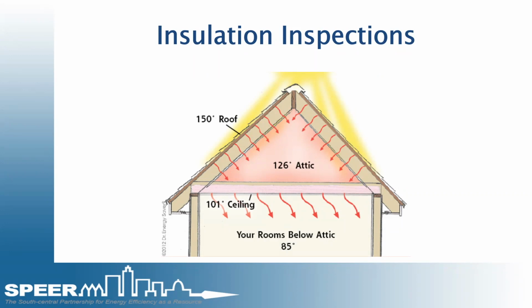Then it hits the sheetrock. Then it starts the process over again. Now it's conduction and it's pushing through the sheetrock, and now it re-radiates itself inside the home. If you can use at any point a way to slow that down, that's what insulation is all about. You slow down the heat transfer through that.